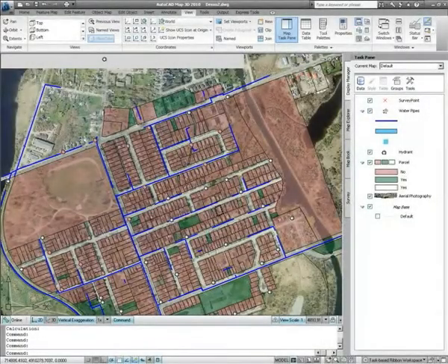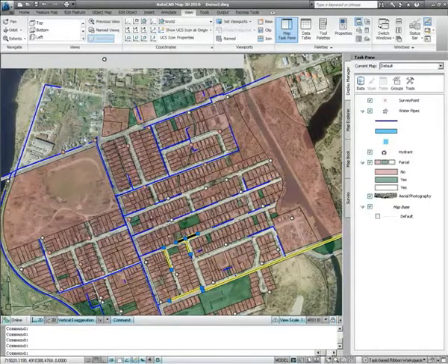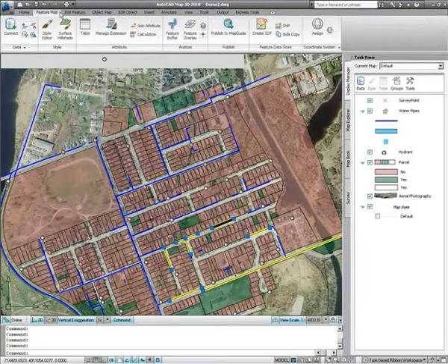The ability to carry out analysis and querying on spatial data is very important to utility customers. For example, you may need to identify properties which will be affected by scheduled work on a waterline and send out notices that service may be interrupted. AutoCAD Map 3D provides a number of tools which will allow you to make the best decisions as to how repair work is carried out.